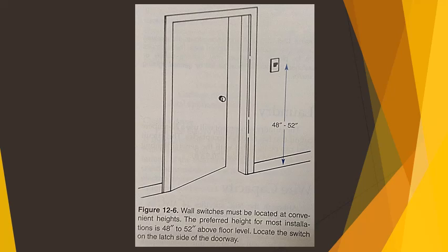The Americans with Disabilities Act, or ADA, a comprehensive civil rights law for people with disabilities, stipulates that the height of wall switches follow these rules. If the clear floor space allows parallel approach by a person in a wheelchair, the maximum high side reach allowed shall be 54 inches. If the wall switch must be accessed by reaching forward, then the maximum height shall be 48 inches.